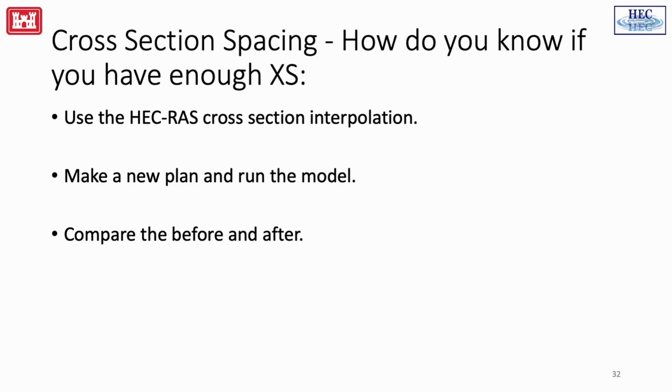When I mentioned this, right, the cross-section interpolation. When you're editing, when you're doing those tests, make copies of your geometry and create new plans so that you can compare them. Don't just work in one plan, edit the plan, rerun the plan, edit the plan, and rerun it, because you're not going to learn as much from that. It's nicer to create more plans and compare them, and you learn a lot more from that.